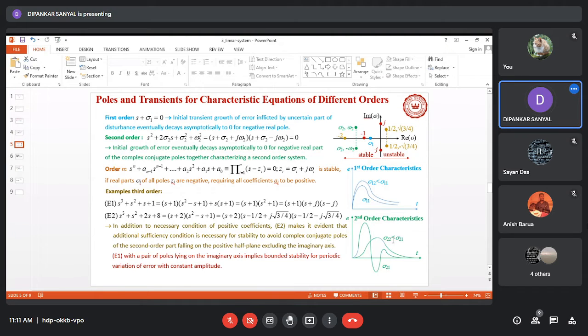If this sigma is small, then this decay will be fairly slow and it will eventually become zero beyond a particular time. But if we keep on increasing the sigma value, we may see some periodic oscillation prior to settlement to zero. When we have this kind of periodic oscillation, though the amplitude of error becomes higher, the settlement to zero occurs at a faster rate.